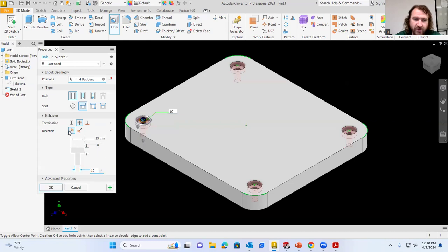So once we enter the values of whatever we're making, there's going to be values given about what type of hole we're making. In this case, we're making a counter bore hole that goes through all the material, and the counter bore diameter is 25. The counter bore depth was 8 millimeters. The diameter of the clearance hole was 10 millimeters, right? And all this information is going to be given to you in some type of part file drawing, and then you just plug in the numbers, okay?